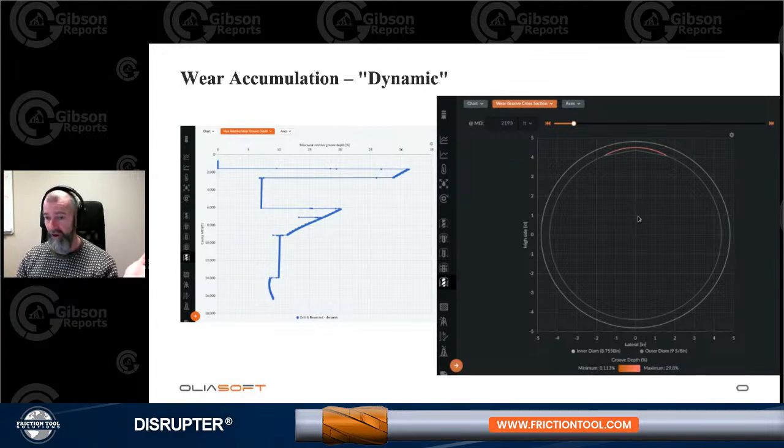Calculating the location of a drill string at a certain point is basically just looking at the tension vector at the bottom and at the top of a segment. Then you combine that with gravity, and you can figure out where the drill string ends up inside the casing. It might not be 100% correct.